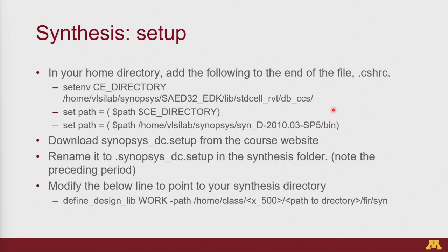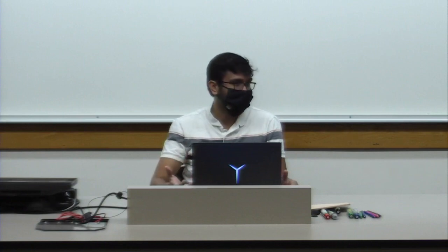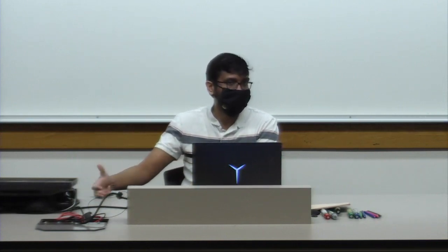So I think we have about 5 minutes left, so I'll quickly wrap this up. The last thing we have is, once we actually design everything, we need to synthesize it to see how good our design is. What synthesis does is convert your Verilog code to actual physical gates, flip-flops, and different kinds of building blocks. And once you do that, you can report the different characteristics of the design.